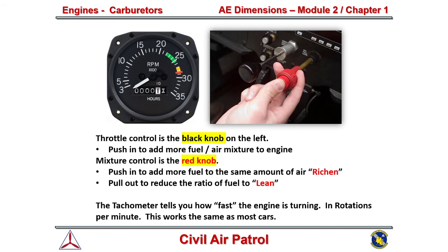Now, that's actually one of the things that makes a car engine different from an airplane engine. Car engines will run, obviously, very nicely in that same range as well, the give or take 2,000 to 2,500 range. But you'll notice in a car that most of the time it will actually gear up, and the RPMs on the engine would actually be reduced. You won't see a car engine sit at 2,200 RPMs the whole time. So the advantage with an aircraft engine is it actually maintains a higher RPM than, say, you would see in a car. Thought that was interesting for you to know.